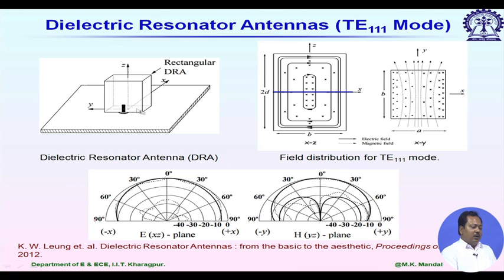It actually shows half of a full resonator, placed on a ground plane. You can see it is being fed by one SMA connector, and the inner conductor of the SMA connector is drilled inside this DRA. You can also see one slot etched in the ground plane. This is to couple power from the SMA cable to the DRA.